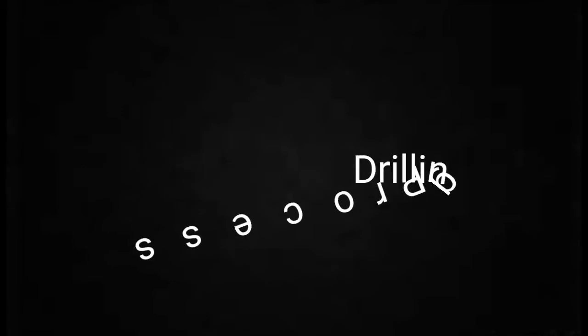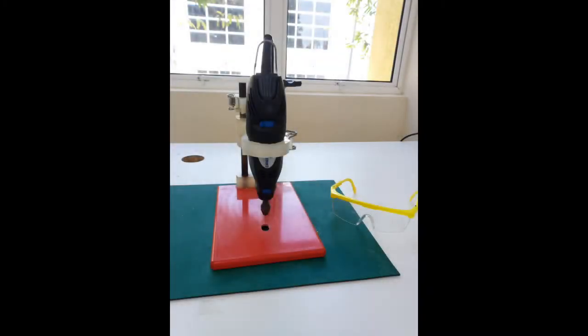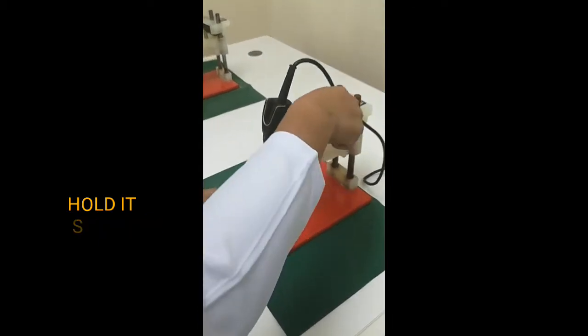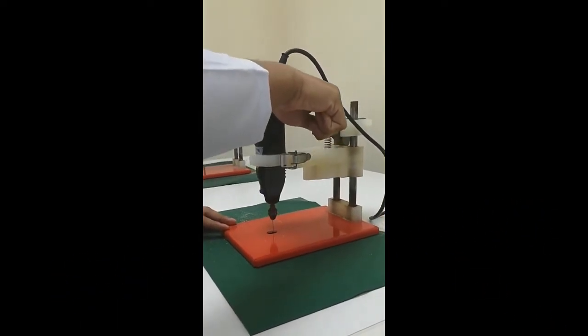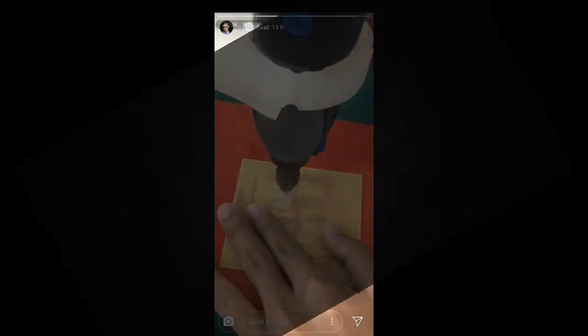This is the drilling process. In this process we make holes on the PCB by using suitable drill bits, which are 0.7 mm and 1 mm. In this process, we need to hold the drill straight and not bend it or move the PCB when the process has started. Make sure all the component holes have been drilled before you start soldering the components on the board.